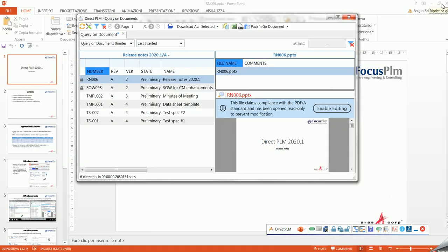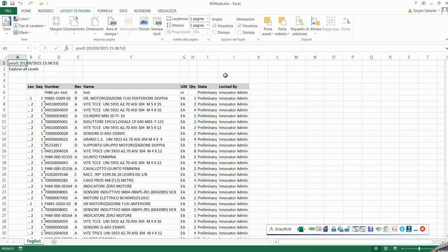Okay, as I said at the beginning, there can be different use cases. Let's follow a different one for an Excel file. Let's suppose that I want to insert this document in ARAS, but in that case, this is an Excel file that actually captures a specific situation of a bill of material for an existing part. So my goal is to associate this document to an existing part. So actually I should follow two different steps. First, create the document in ARAS and then associate it with the part. Thanks to the connector, I can do both things in a single step.